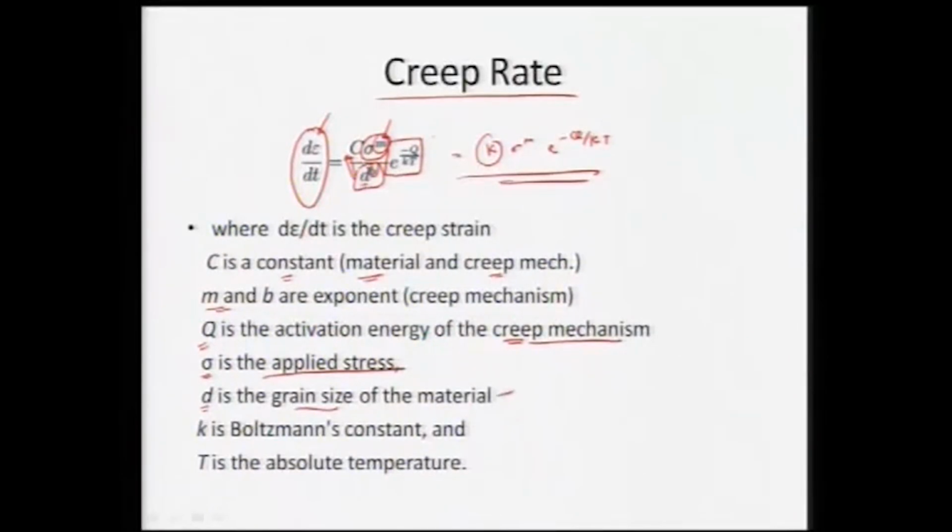So, we can see that for a nanocrystalline material, the grain size has to be very high, or the grain boundary area has to be very minimal in this particular case, and K is the Boltzmann constant, T is the absolute temperature. So, in that case we can see that nanocrystalline grains do not serve as good resistors to the enhanced creep rate. So, to restrain the creep, we always need a very coarse grained material.